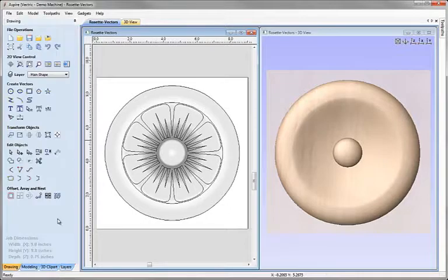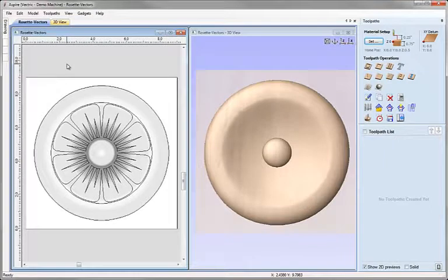I'm going to click on the Drawing tab here, come up and click on the icon to switch to Toolpaths tab, and we'll see that the Design tabs have now been hidden on the left, Toolpaths tab's been opened on the right. Now first I want to calculate my rough and finished toolpaths for my 3D, but as with any job, before we calculate toolpaths, what we want to do is double check our material setup.